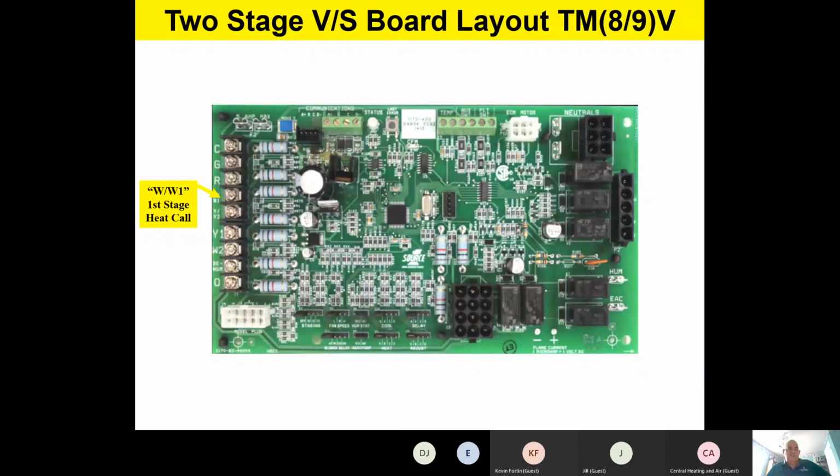So W/W1 is our first stage heating call. Y/Y2 is our second stage cooling call. Again, it's a two-stage heat, two-stage cool capable board. Y1 is our first stage cooling if you have a two-stage product outside. W2 is our second stage heating call.